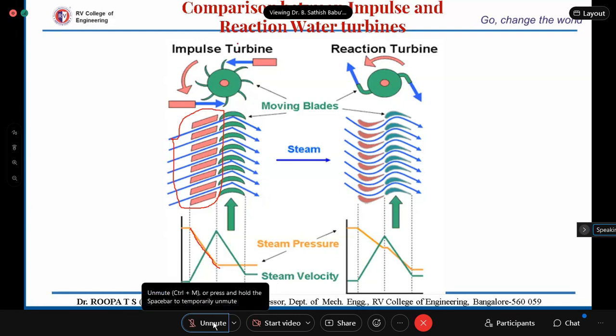In an impulse turbine, there will not be the fixed and moving blade concept, because whatever pressure and velocity changes there are are achieved through the nozzle. So here we will be using the nozzle, wherein as soon as the steam passes through it, its pressure decreases and velocity increases. This region represents the nozzle region. Next are the moving blades, which have a uniform cross section.